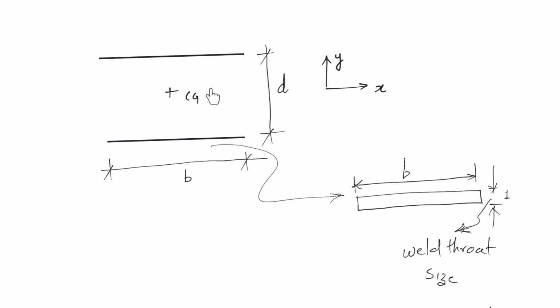So Ixx will be the second moment of area about this axis, which is pretty straightforward because we have two areas over here. Using the parallel axis theorem, assume I have a parallel axis to x passing through this area; its moment of inertia about this axis will be very small because you have a b1 cube, b1 cube divided by 12. Let's ignore it. But using the parallel axis theorem, what happens?